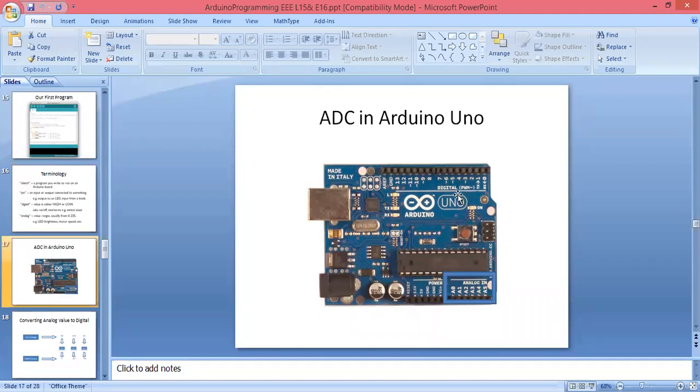Here it is written digital, in bracket PWM. PWM means what? If we have to use pulse width modulation, if we have to interface any analog device with the Arduino Uno board, that will be pulse width modulation. Then we can use that as a tilde pin. In this tilde pin, any pin we can connect as a PWM output.